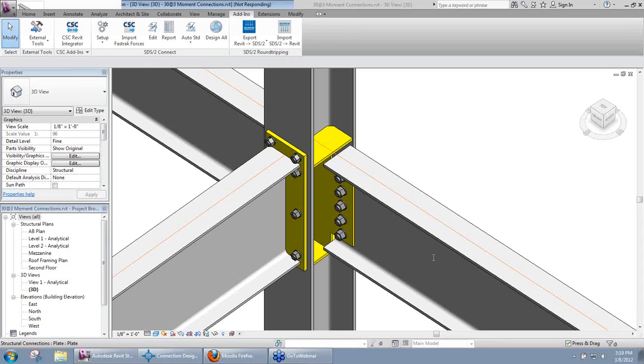I guess one of the big ones I'll just throw out there, because it's come up a few times in the last couple of weeks, is shear plates through to a tube column with a through plate. We can't design that when there is actually an axial load applied. So that would be just one case where we don't analyze a connection.